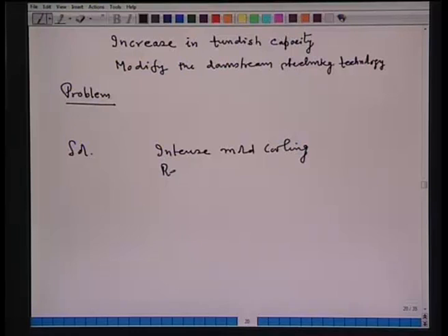in the conventional slab casters you have some diameter of the nozzle. If you use the same diameter of the nozzle, then velocity of the steel melt entering the mold will increase. So, you have more turbulence in the mold. So, you have to redesign the submerged entry nozzle. This is needed only because the length of the mold you are not going to increase, it will remain between 0.9 to 1 meter. So, these are the two issues, for example, in case of mold.